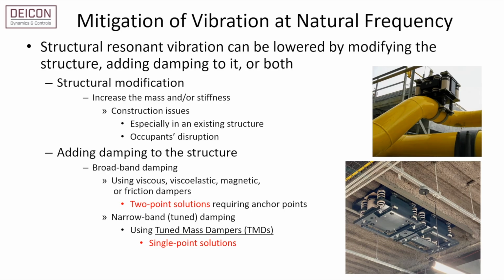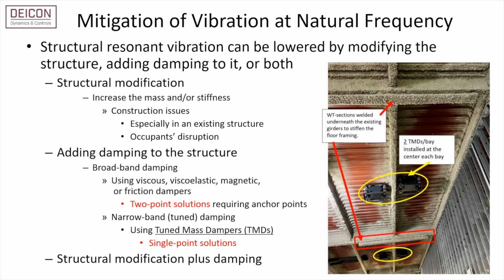In applications where strict vibration standards must be met, a blend of solutions could be necessary. For instance, in the scenario depicted in this image, the vibration levels in a medical facility operating room floors were reduced to meet specified standards. This was achieved by reinforcing certain beams to add stiffness and strategically installing tuned mass dampers beneath the floor system to add damping to it.